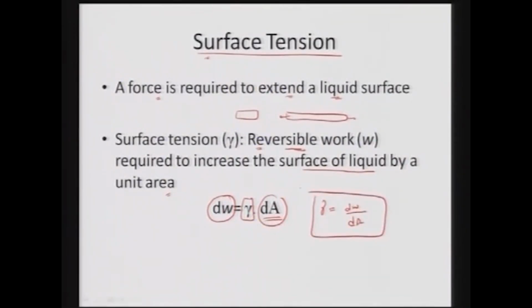And surface tension is mainly responsible for the spheroidization of a liquid particle. We'll realize that surface tension is equivalent to surface energy for liquids, whereas it is not so in the case of solids. Surface tension is the one which causes deformation of a surface because of this additional force which exists and does work on the liquid.